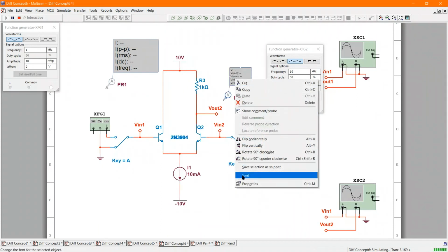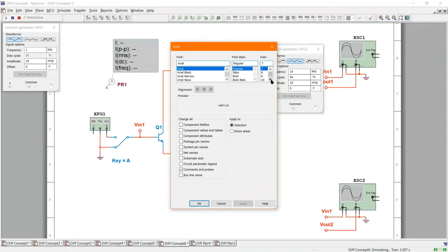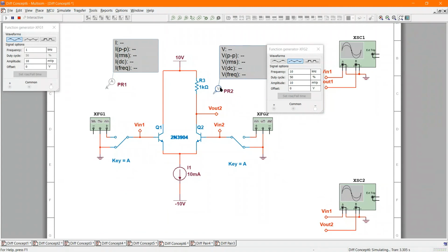this point, just make this a little bigger. So that means if this guy is dropping 5 volts and we started with 10, then this point here should be about 5.18 volts. So this was 4.8 drop, that's about 5.2. So there you go. You don't need the second resistor for it to bias correctly. And we don't need a resistor down here. We can replace it with a current source. So the DC doesn't seem to be affected much by these changes.